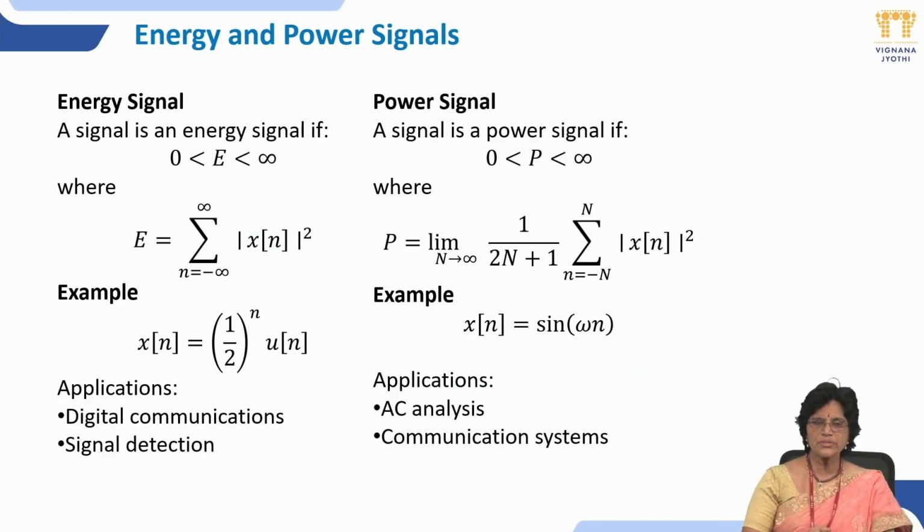In this case also you will get small problems. You have to check whether the given signal is energy or power. If it is a power signal, calculate the power of the given signal. So first state whether it is power or not. After that you have to compute that value too.